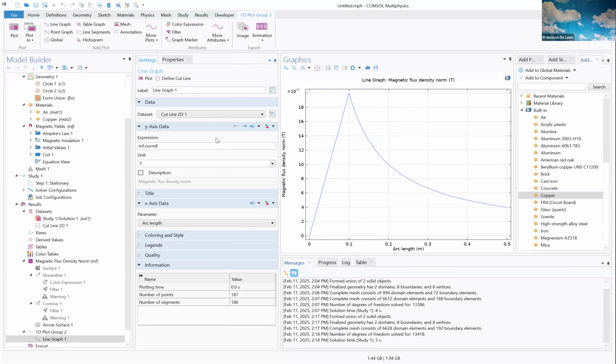The reason is that you're violating the continuity of current. You are injecting current without it coming back in the model. So it needs to come back somewhere, otherwise you are not solving a physical problem. This is a typical illustration, but in physical reality, the current needs to come back somewhere.